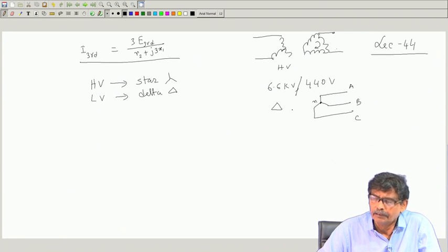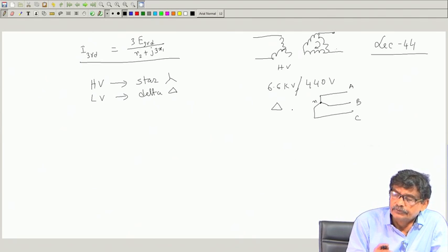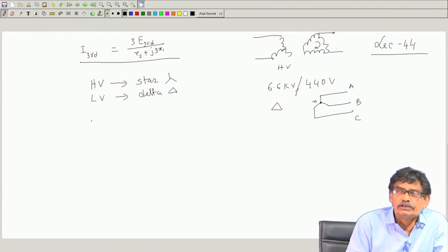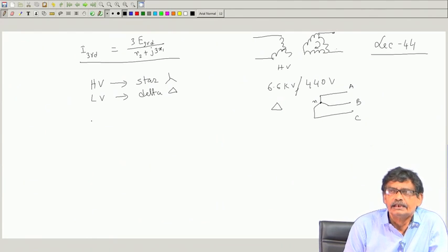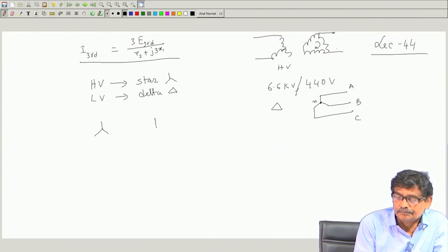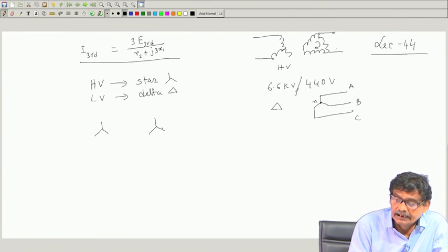And sometimes if the voltages are high, what people do is use star on both sides, relatively high voltages. So, then select star-star, but with star-star there are problems we have seen. What people will do is they will also put another coil which will be delta connected.